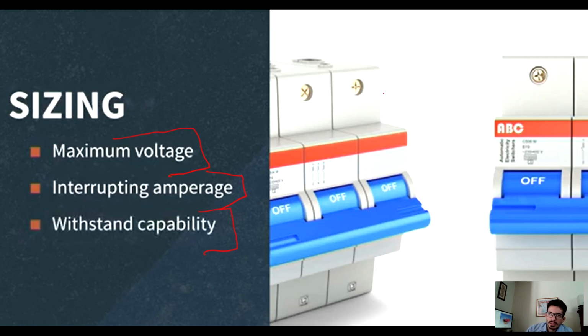The main thing I want to mention is learn how to connect them. Remember, the contacting and the connecting part is crucial, so you connect them by screws. Never operate, install, or uninstall breakers if the panel board is not completely off. Meaning, if there's power going to the panel board, never try to switch a breaker. Make sure that the panel board has no power going into it. This is by the tag out standard. You can make sure that it's not powered.